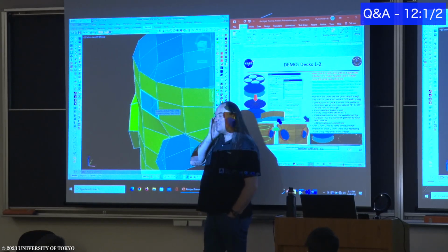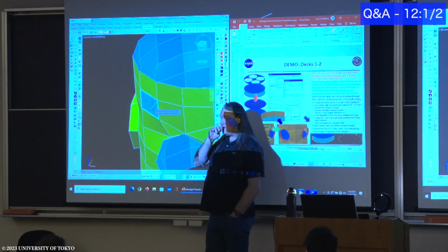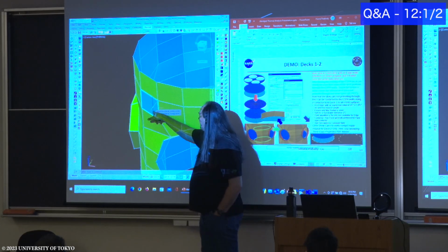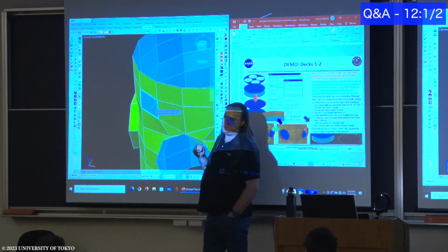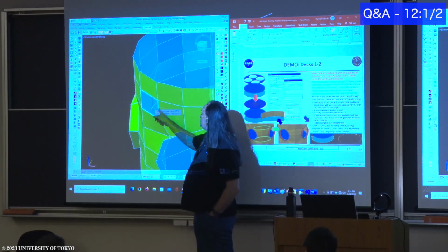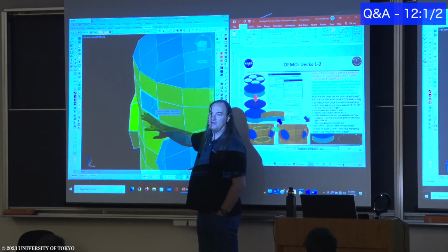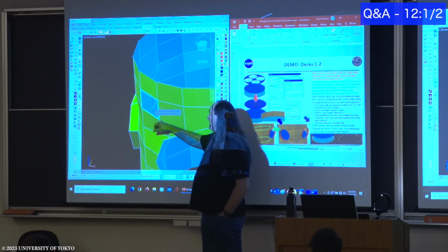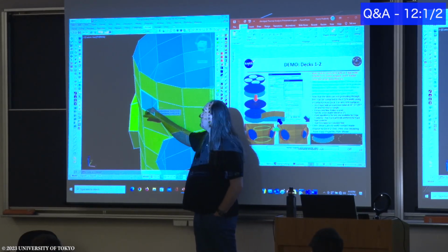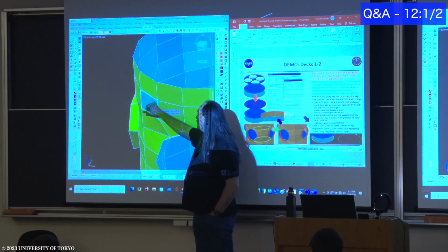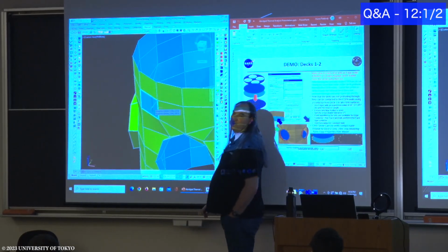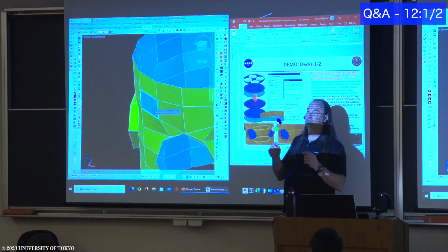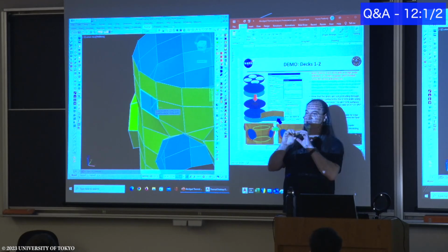I believe that TSS, which was a precursor to that, used a subdivision, so it would divide this, and if it hit into this corner, all of the energy went to that node. The area for this is just geometric if you look at the whole element, but if you're trying to see the sub-area associated with each of these, again, I think those shape functions distribute it differently. More of it goes as you're closer to the node. So it's not all of it goes into one node. It is spread out based on the distance between the location where the ray hit and the rest of the nodes.